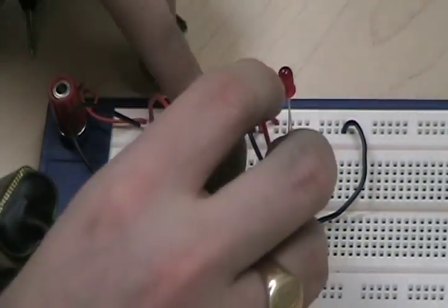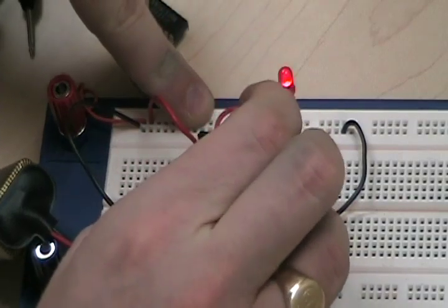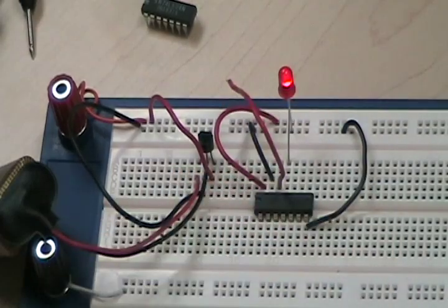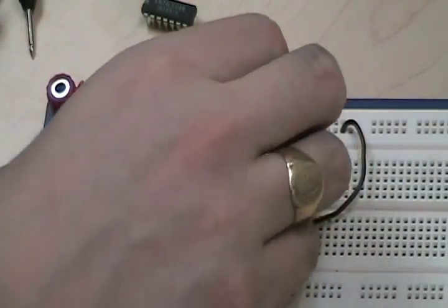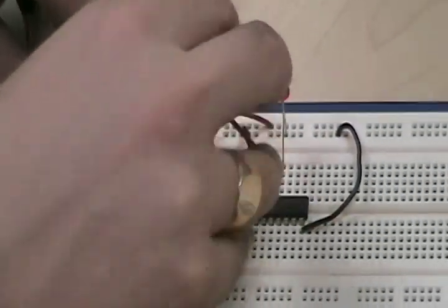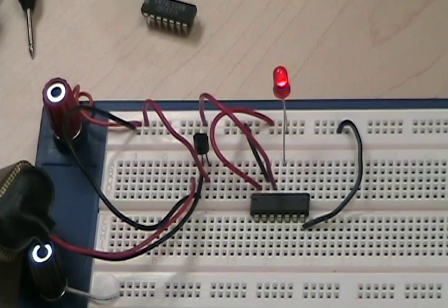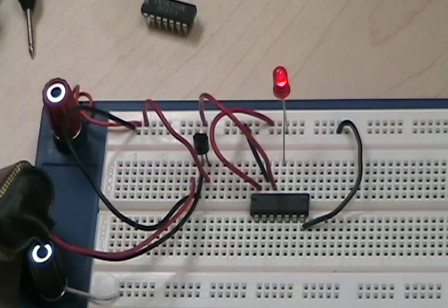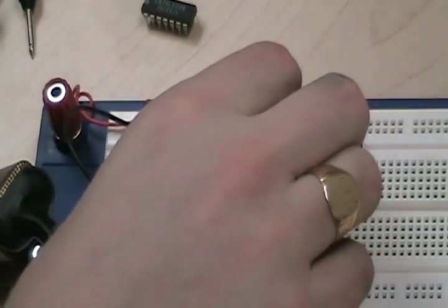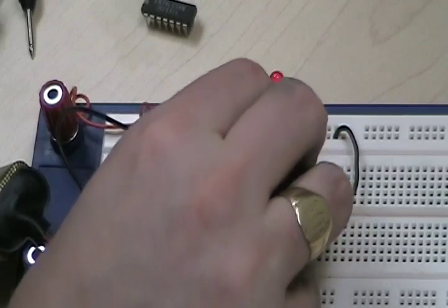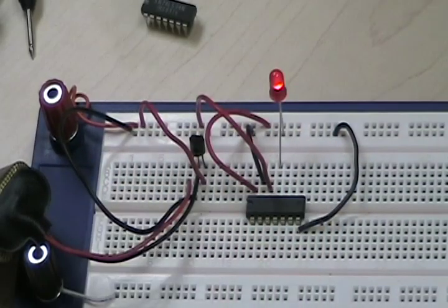As soon as I take any of those off the ground line and leave it floating, it's automatically assuming a power level of 1, or a logic level of 1 rather. High or low logic. 5 volts, high logic. 0 volts, 0 logic. So now one input is grounded, one input is not grounded, one input is held at high. So I can do whatever I want with that second one. I can ground it, I can put it at 5 volts, it doesn't matter, because one of the inputs is already at high logic.